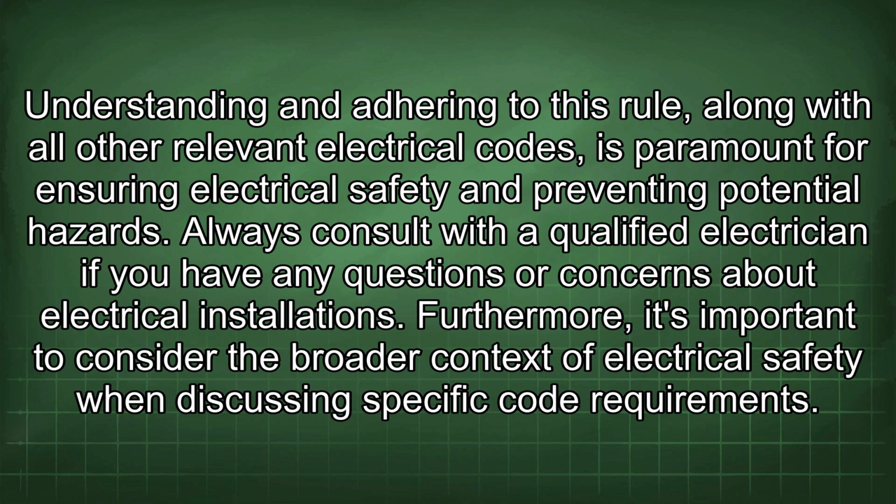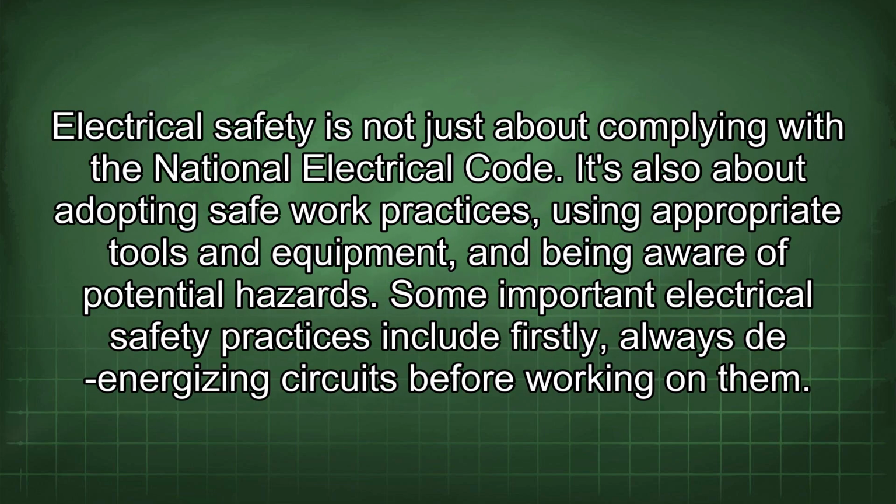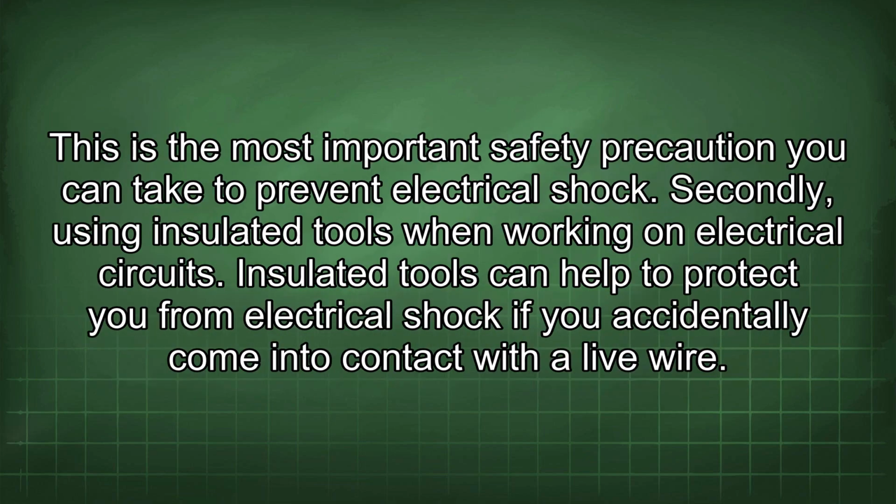Furthermore, it's important to consider the broader context of electrical safety when discussing specific code requirements. Electrical safety is not just about complying with the National Electrical Code. It's also about adopting safe work practices, using appropriate tools and equipment, and being aware of potential hazards. Some important electrical safety practices include, firstly, always de-energizing circuits before working on them. This is the most important safety precaution you can take to prevent electrical shock.